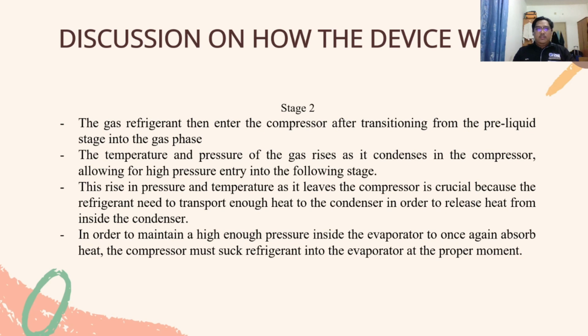For stage 2, the gas refrigerant enters the compressor after transitioning from the pre-liquid stage into the gas phase. The temperature and pressure of the gas rise as it is compressed in the compressor, allowing for high pressure entry into the following stage. This rise in pressure and temperature as it leaves the compressor is crucial because the refrigerant needs to transport enough heat to the condenser in order to release heat from inside the condenser.